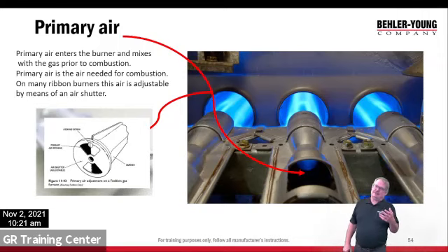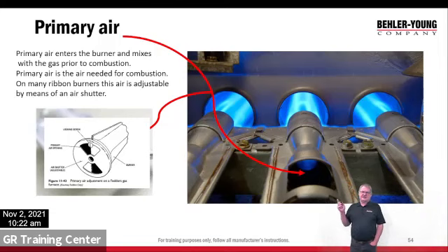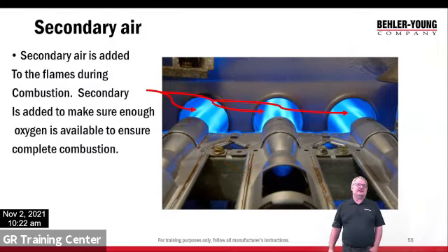Nowadays, we do combustion tests, so we're a little more accurate in setting these burners. If that shutter got closed, or got full of dirt or lint, we didn't get complete combustion anymore, and that's when we started sooting and producing carbon monoxide. Most modern furnaces aren't adjustable, but there are still a lot of old timers out there that you can adjust.